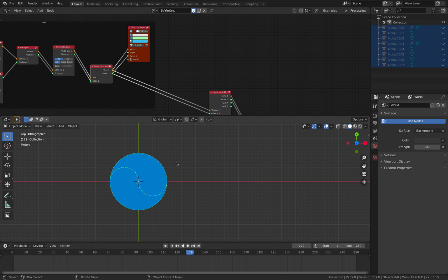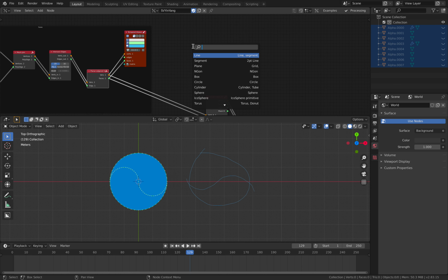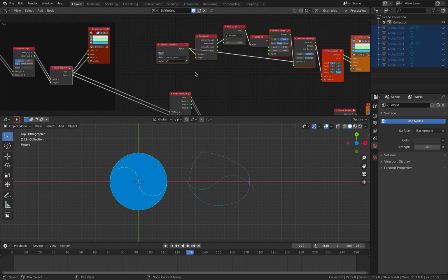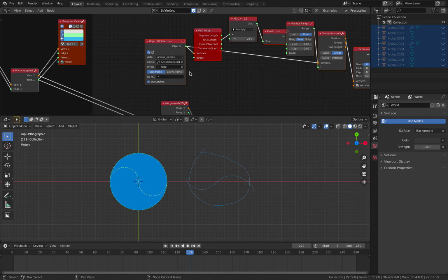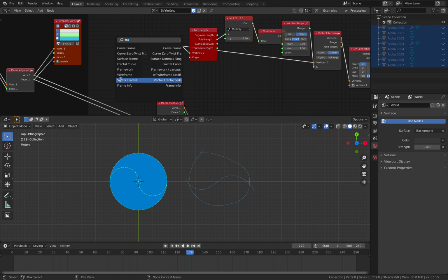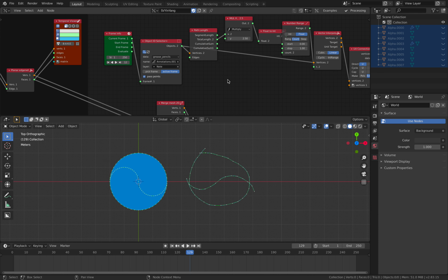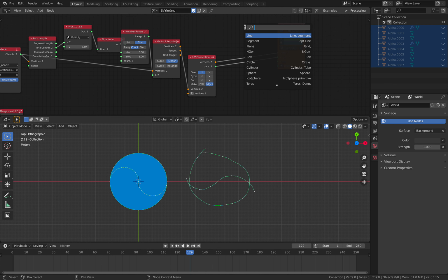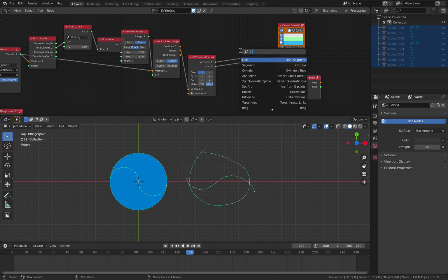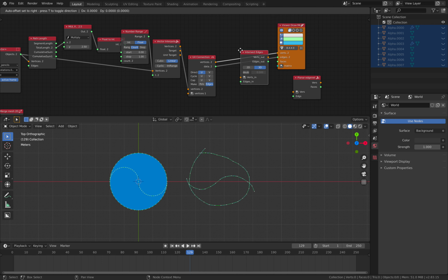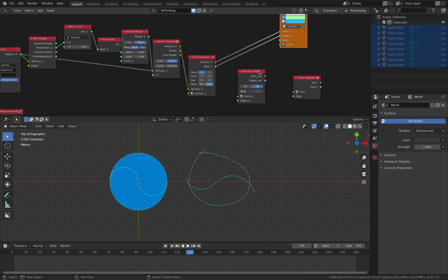So if you actually design this using a grease pencil, if I make a really badly drawn grease pencil like that, you can use the GP macro, grab the annotation grease pencil, and if you use it with Planar Edgenet and Intersect, this will basically do the same.